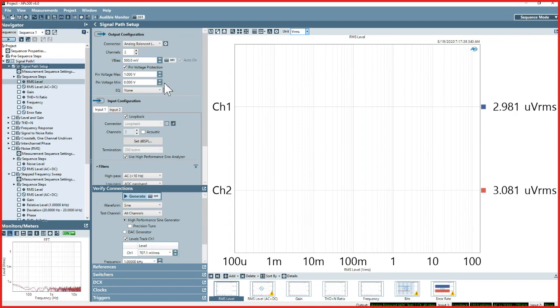Okay, if that did not satisfy the questioner, please feel free to follow up with another chat and we can address that as well. So finishing up here, just where is the application for common mode DC? The reason we call it ADC test is that this arises primarily in the case where we're testing ADCs that are designed to be interfaced directly to something like an electret microphone, where there's going to be a DC bias present, and we want to essentially simulate that.